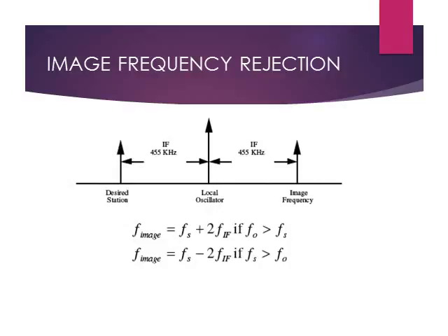Now, image frequency rejection is an important issue in FM receivers. In heterodyne receivers, an image frequency is an undesired input frequency equal to the carrier frequency plus twice the intermediate frequency. The image frequency results in two stations being received at the same time, thus producing interference and undesired results. But fortunately, it is possible to remove the unwanted signal by the addition of a tuned circuit prior to the mixer. The local oscillator and RF amplifier are ganged or tuned together for this purpose.